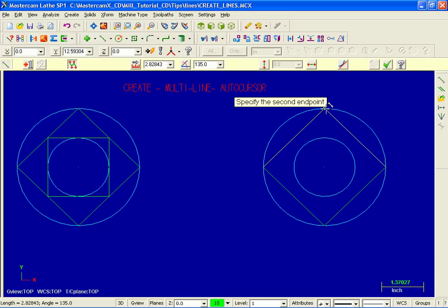and quadrant. Now in these cases auto cursor uses a specific order to detect and snap to points. Now the order starts with point entities, then endpoints of curves or lines, then it moves on to midpoints, and then next it moves on to quadrants. So what's happening here is I only have quadrant and endpoint turned on, but endpoint is closer up the top